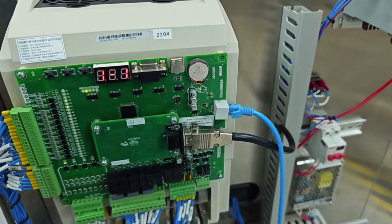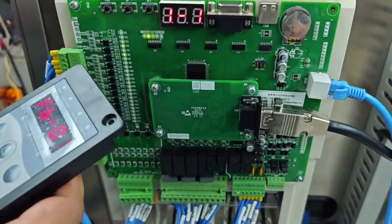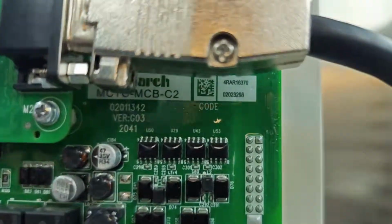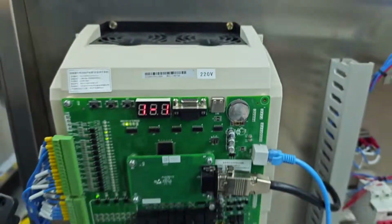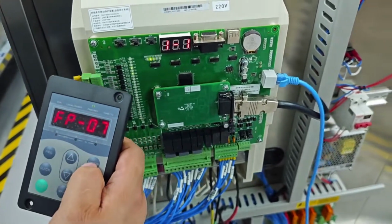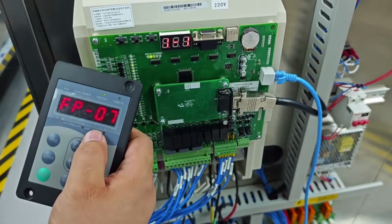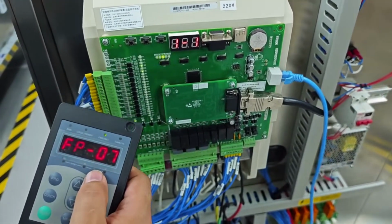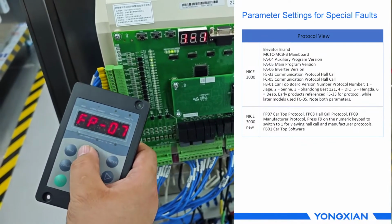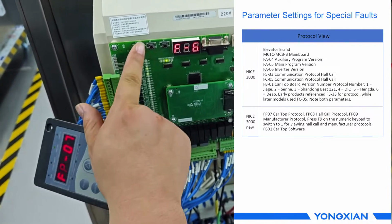Early products reference F533 for protocol, while later models use FC05. Note both parameters. If it is the new NICE3000new board like MCTC-MCB-C1 or C2, look at FP-07 for the car-top protocol, FP08 for the hall call protocol, and FP09 for the manufacturer protocol.